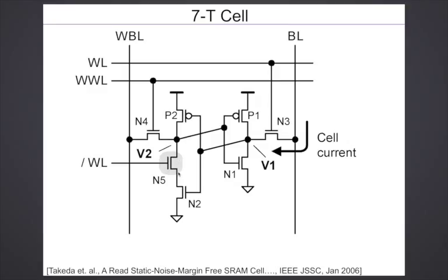So the question is again related to what your friend asked. The N5 being in series, how will that impact the VDD and so on? As I said, the VDD scaling, it will have some impact. It's a very, very small impact compared to the limitations of VDD coming due to process variation. And really the threshold voltages can change by 50 to 100 millivolts, 150 millivolts. It can change by a large amount, right? So that really causes the limitation.